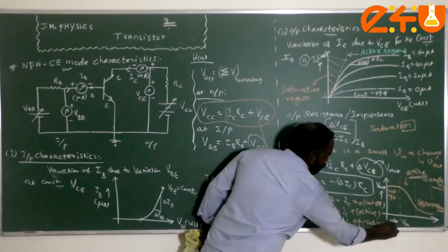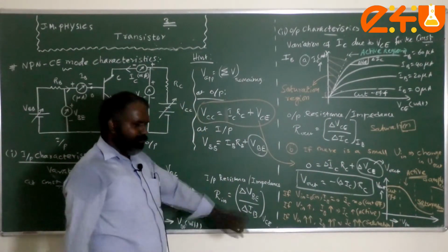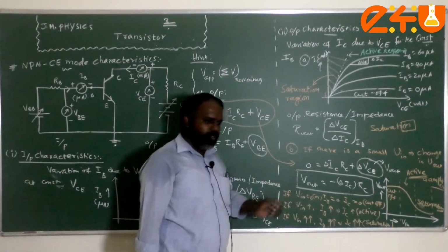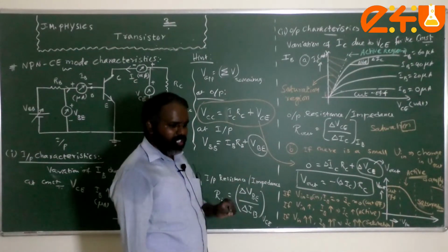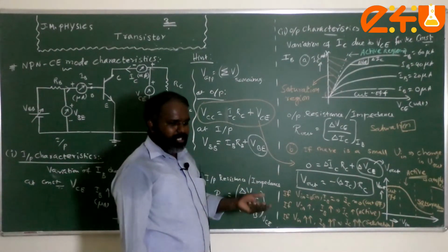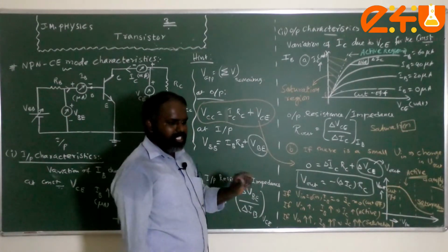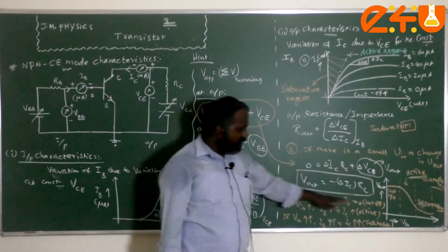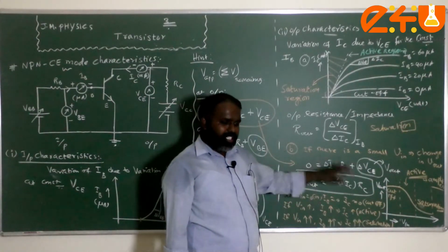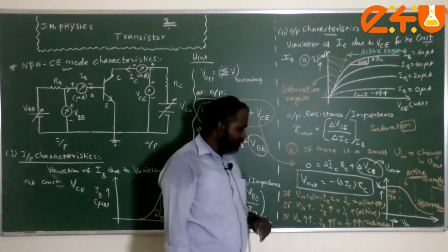If we want to use the transistor as an electronic switch: we know mechanical switches like a switchboard are very big in size, but when you make smaller electronic circuits, we cannot use such mechanical switches. Instead, a small transistor can be used as a switch. By maintaining the transistor under the cutoff condition, it acts as the off state. That means there is no flow of current in the circuit.